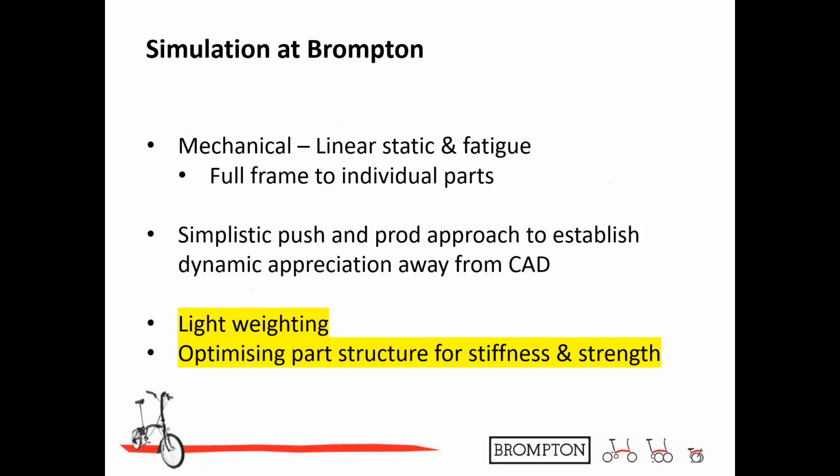So the type of simulation we're looking at, again, very simple. I want to keep this quite basic. It's linear, static, and some fatigue analysis. We'll do a full frame set down to individual parts. I'm really keen to get the designers to just start to take the design away from CAD, not just models in the workshop, but to simply do a push and a prod approach to be able to understand the structural stiffness of the parts and assemblies they're working on.